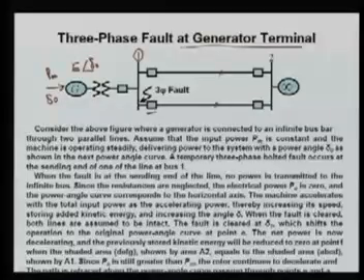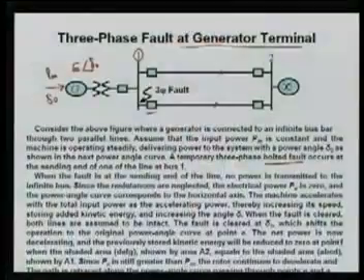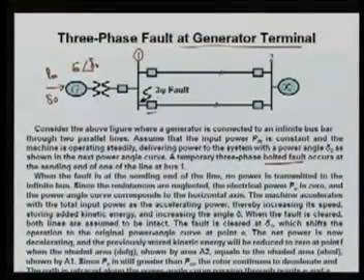A temporary three-phase fault, that is a bolted fault, meaning a fault without any earth fault resistance, directly three-phase to ground, occurs at the sending end of one of the transmission lines at bus 1. Here, let's suppose the three-phase fault has occurred in line 2.